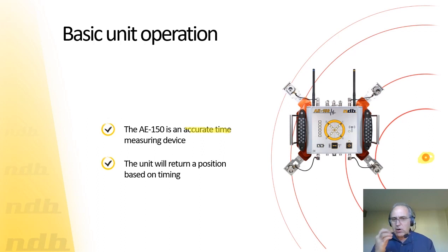They are pressure waves that are flowing in the oil, and as they flow, it takes time to reach each point. So the first sensor to be hit by the pressure wave is sensor number 4, and then it's number 1 as it continues to flow into the oil and steel, and then sensor number 3 gets hit, and the last one that gets hit is number 2.